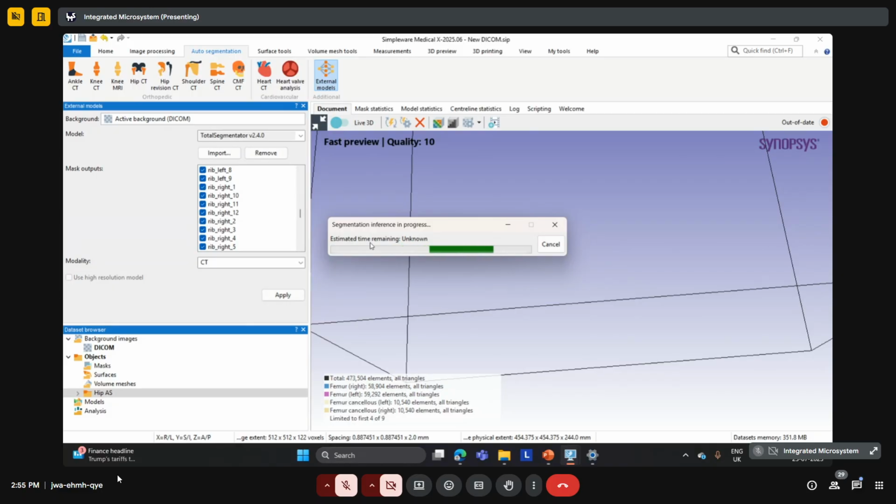So one might ask what sort of operation we can use. Whenever we are working with such tools, we can use local surface correction to correct the surface, followed by a smart mask smoothing or a recursive Gaussian. And ultimately, the surface that we would be getting would be a high quality surface, and we can definitely rely on the segmentation quality for the same.